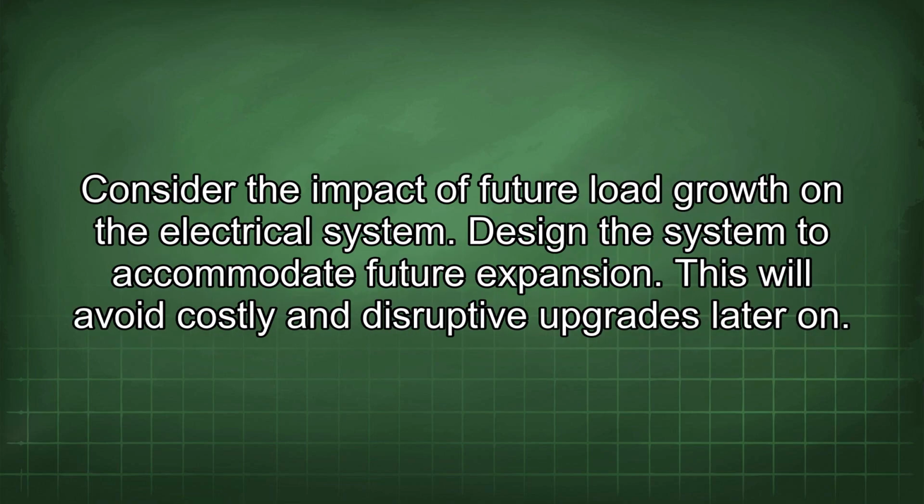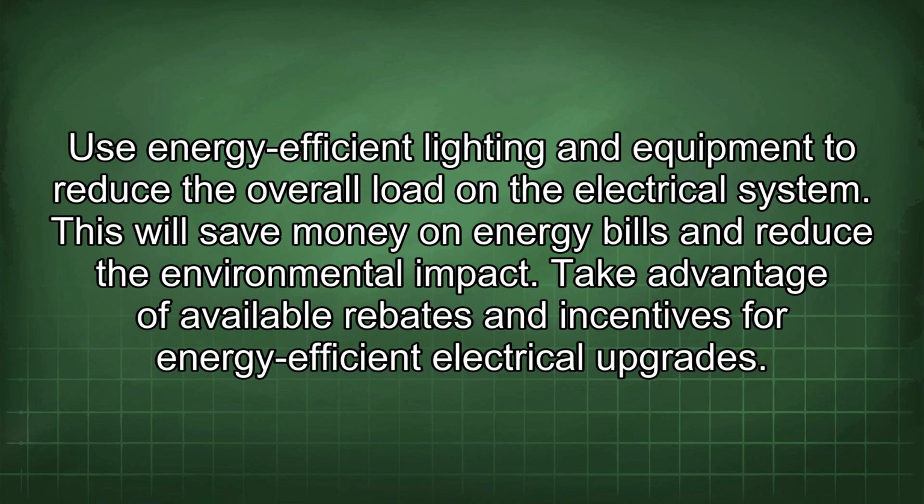Consider the impact of future load growth in the electrical system. Design the system to accommodate future expansion. This will avoid costly and disruptive upgrades later on. Use energy-efficient lighting and equipment to reduce the overall load on the electrical system. This will save money on energy bills and reduce the environmental impact.